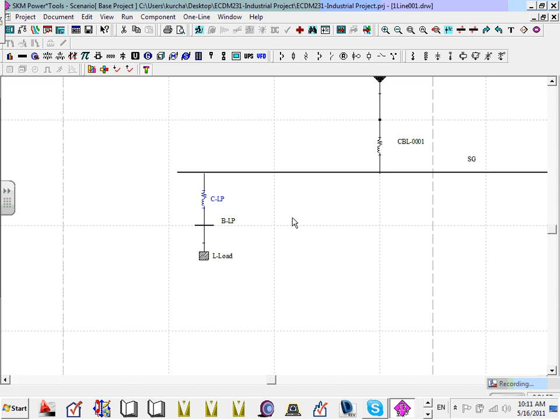Now we're gonna clone. Do you guys remember we have a lighting panel? So what else do I have? I also have bus duct 480. The bus duct 480, we're gonna model it as basically a cable and a chunk of load. So I'm gonna use the same scenario here and clone it. Look what I'm gonna do, guys. Very easy. Highlight from right to left. Can you guys see I picked everything? I go one more time. Click and window on it. Everybody knows how to pick it up from right to left. Start here and pick them up.